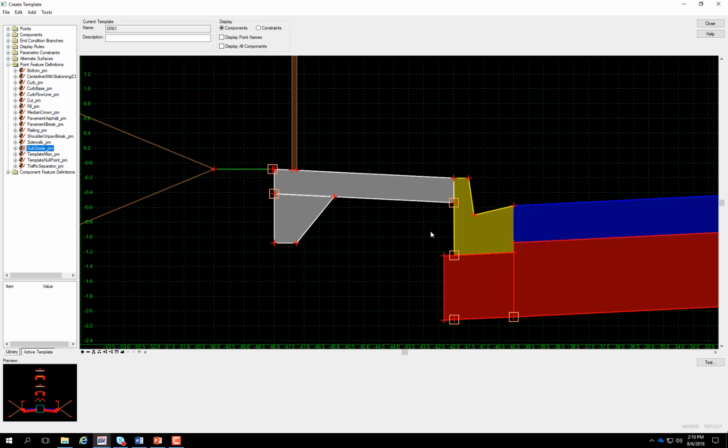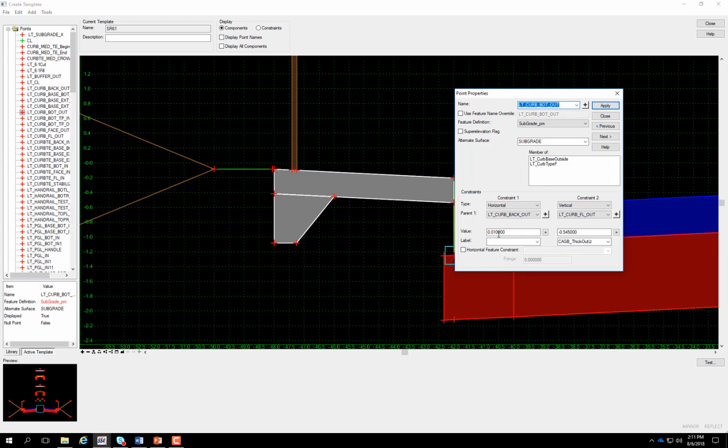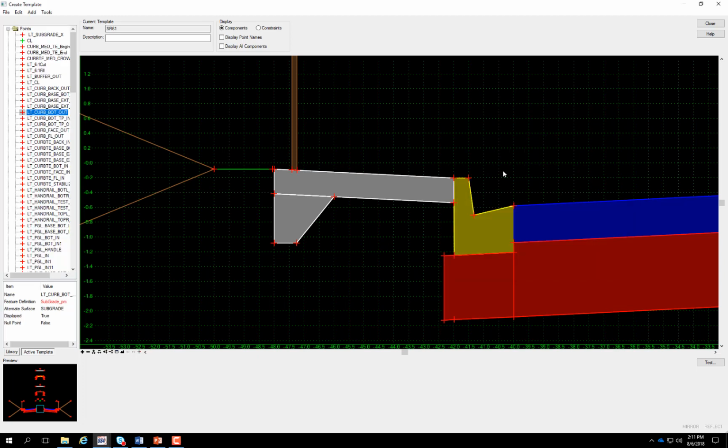The other thing you'll note is whenever there's a point that looks like it's truly vertical, what I've actually done is I've gone in and created an offset. If you look at this point, it's set to -42. However, this point right here, which is typically right below it at a horizontal offset of 0, now has a small offset to the side that the triangle would form. In this case, it's a plus 0.01. That'll prevent it from being a truly vertical surface. It just needs a small horizontal distance in order for that to be created.